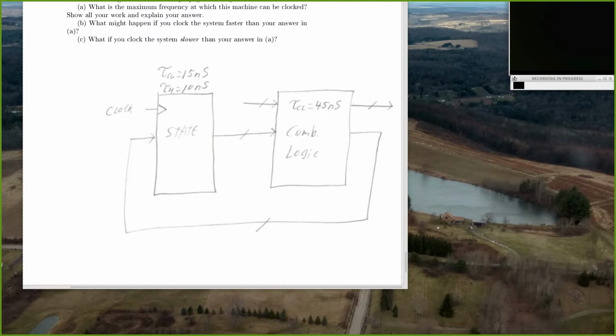If you don't want to repeat the 2 D flip-flops, times 3, because you're already doing that in experiment 1. But you need to somehow tell the person what pins to put wires into. And so your best bet is in your schematic for experiment 2, include the D flip-flops in that delay circuit with part numbers and pin numbers and so on and so forth. So I'm just going to go ahead and say that.